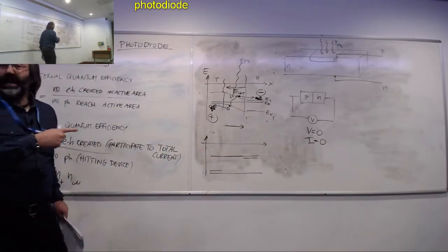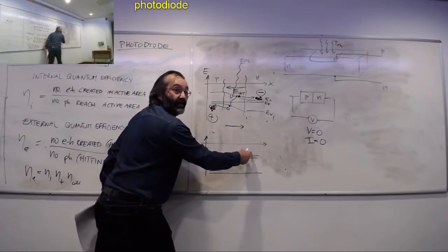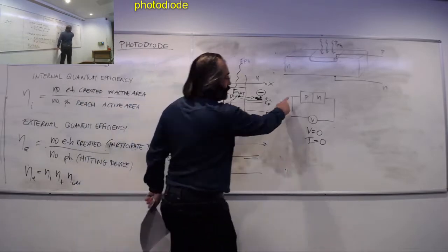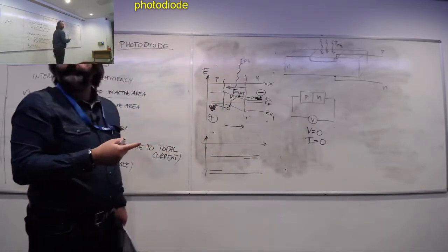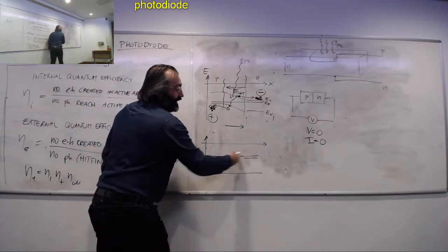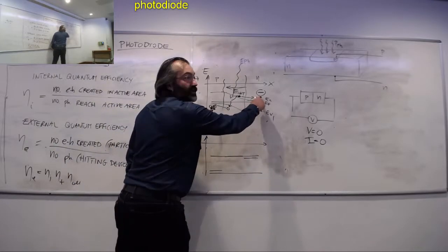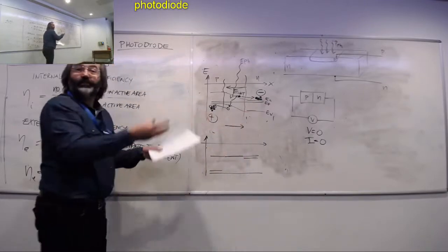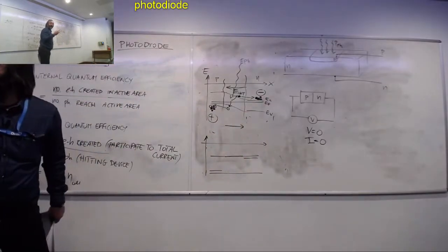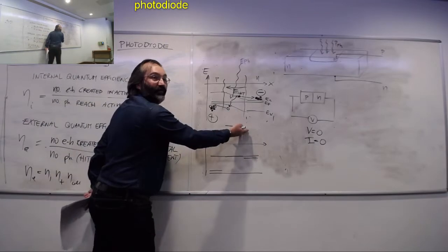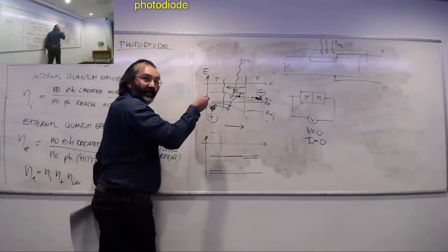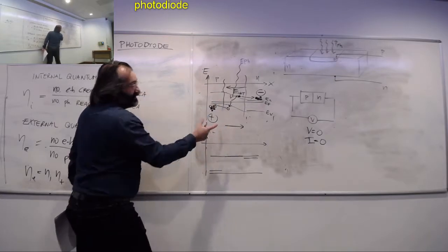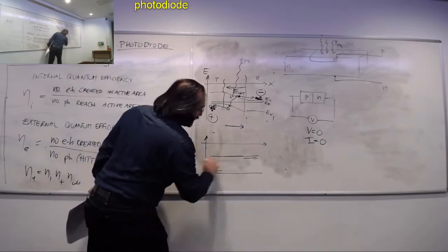If that was to happen, electrons from here would flow there. And this is not allowed because this is not connected to anything, first of all. And second, eventually, this would reduce the charges there, reducing further the electric field. And so that's how we can realize that really the maximum field I could ever generate with this approach of light just going on the p-n junction is as much as the internal one, such as to generate this picture.